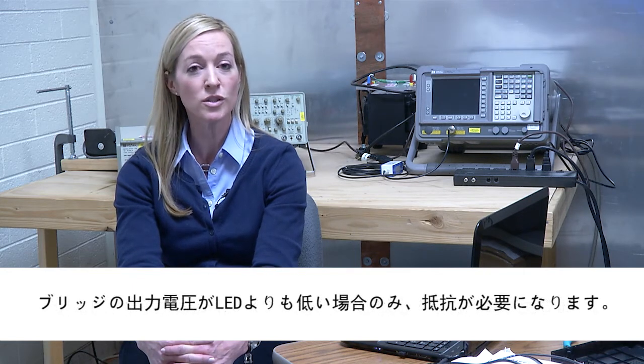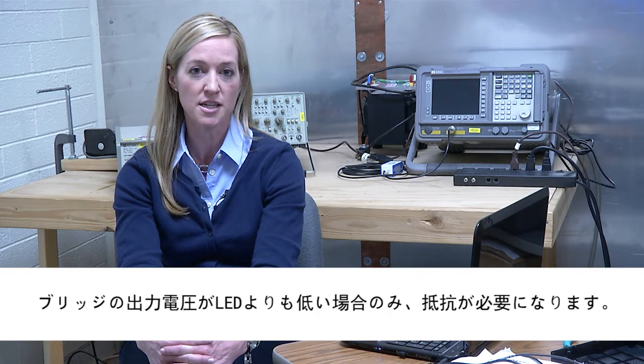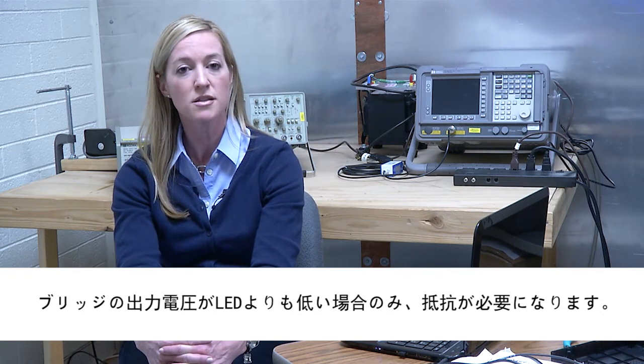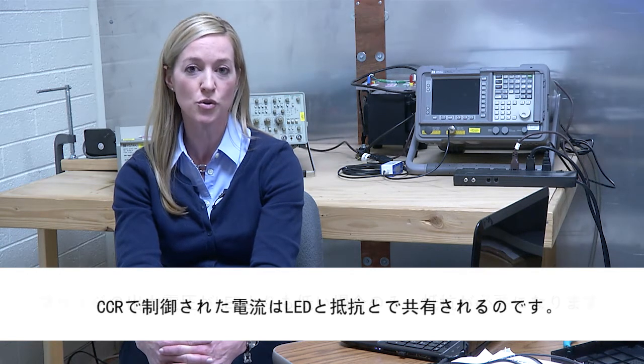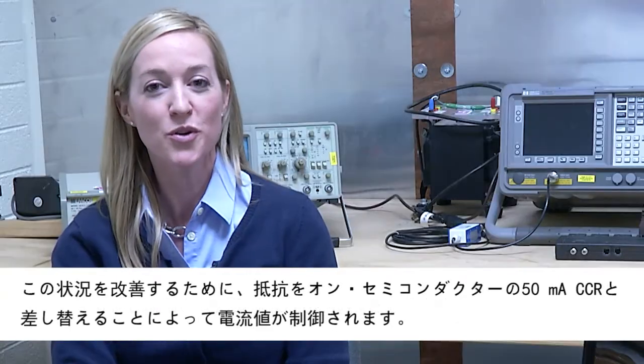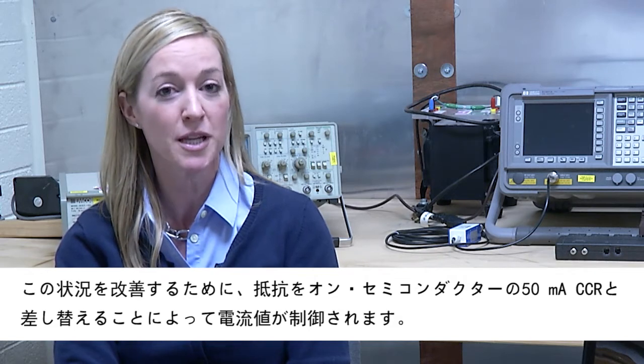The resistor is only needed when the voltage out of the bridge is below that of the LEDs. By placing the resistor across the LEDs compared to across the bridge, the CCR can help limit the current through the resistor. The current being controlled by the CCR would be shared by the LEDs and the resistor. To improve this, the resistor is replaced with a 50 milliamp CCR and the current will be limited.